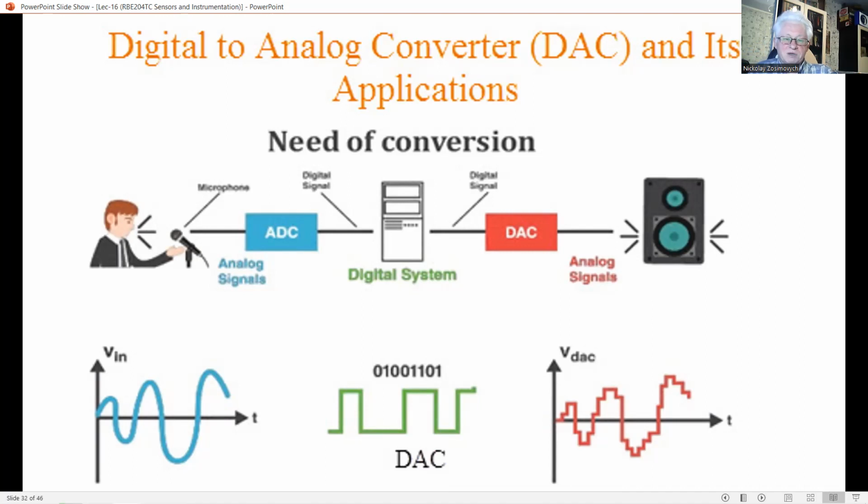Some form of interpolation has to be used to connect and smooth the resulting discrete analog values for forming the analog signal. Typically, the data in the DAC register are arriving from the data bus of the computer to which the DAC is connected.